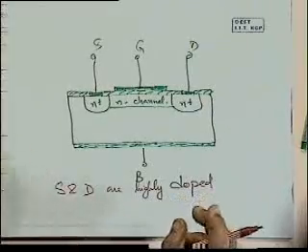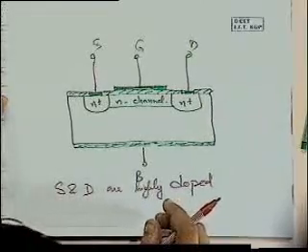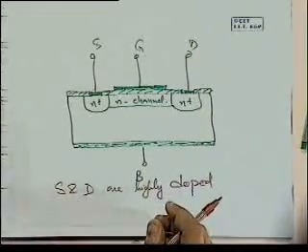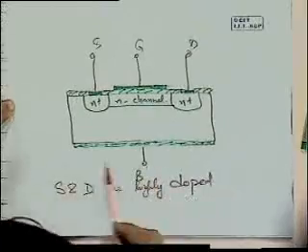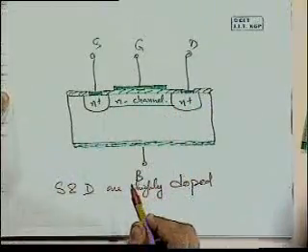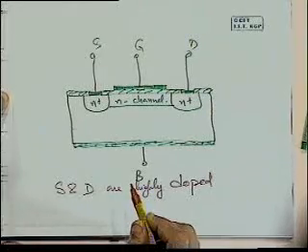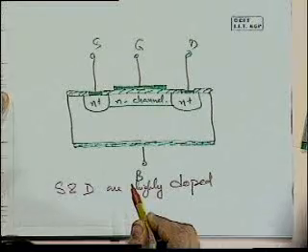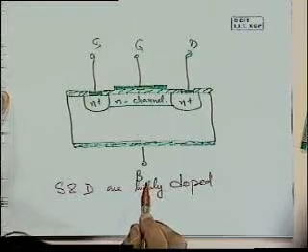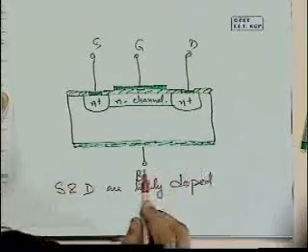Can you suggest why? From what you might remember of Schottky and ohmic and all that, if this area is N plus, why will we get good contacts? How does, let's say, barrier height vary with doping concentration, or does it?